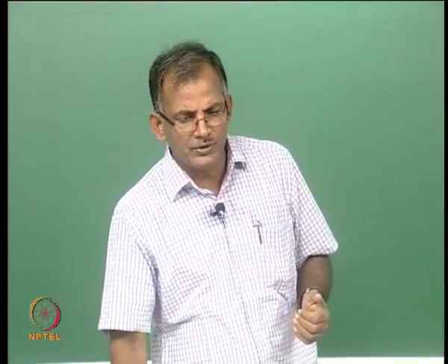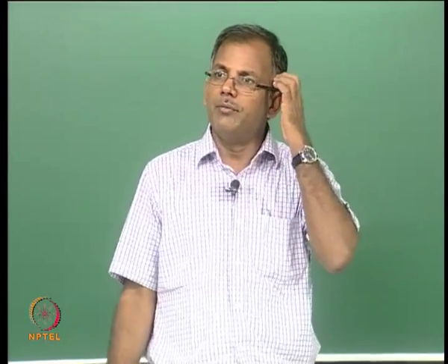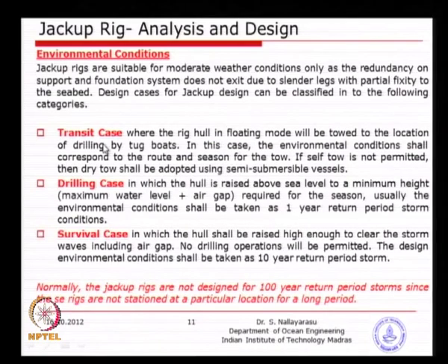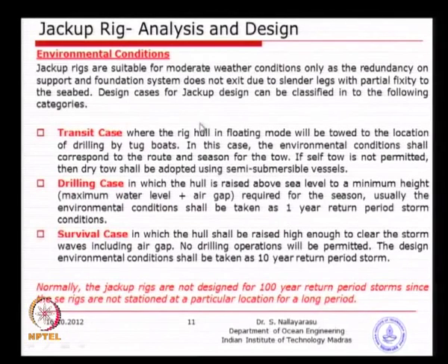You basically do not have to design for all the transit conditions. That means along the route you have several sea conditions which you do not need to design for, because anyway it is sitting safely on a ship. So, that is where the transit case depends on each time when you are transporting. Of course, if it is a short tow of, say, a few hundred kilometers, then you have to re-verify. So, every time you actually use this jackup for a new location, the transit case needs to be verified.